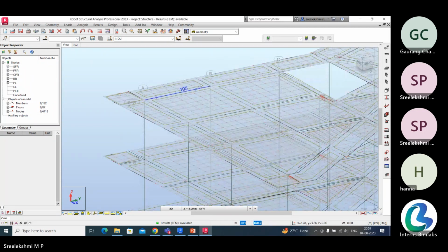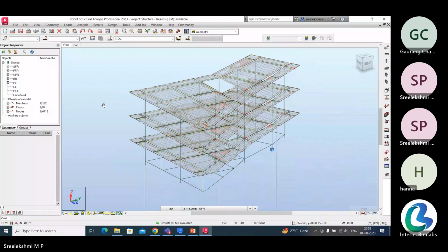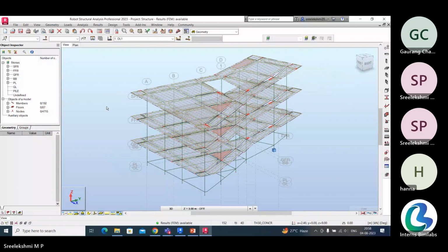So in this way we have to find out which is the proper number, then you have to resolve that in Revit itself. Okay, why? Because we created the parent model in Revit. So we just run the calculation, and if there is no error, then we can take the result. For taking results from geometry, we have to go to results. So we have result diagrams, result maps, detailed analysis, extra tables. You can take any option.